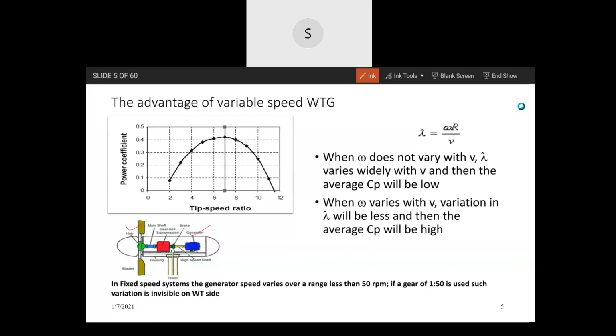For the induction machine, for the electrical generator, power is linked with the speed. Now come to the turbine characteristic, which I'm showing. It is telling exactly the same thing. Lambda, the tip speed ratio, also has the speed, omega, in it. So the speed is linked with the power. For any machine, electrical or mechanical, the speed is linked with the power.